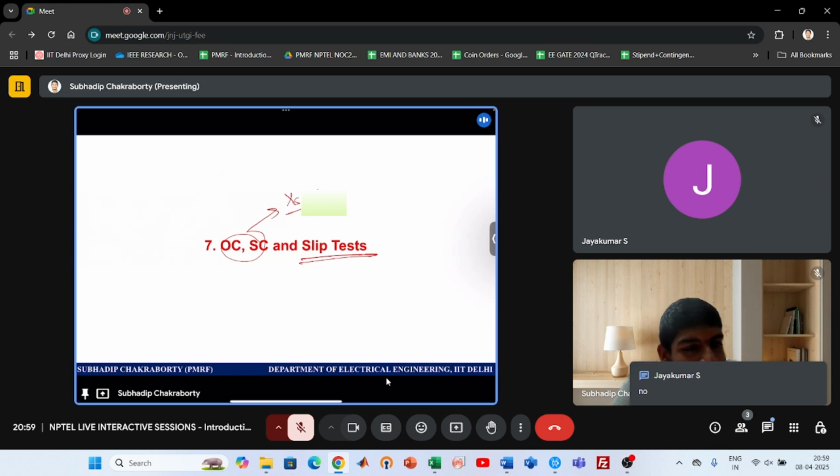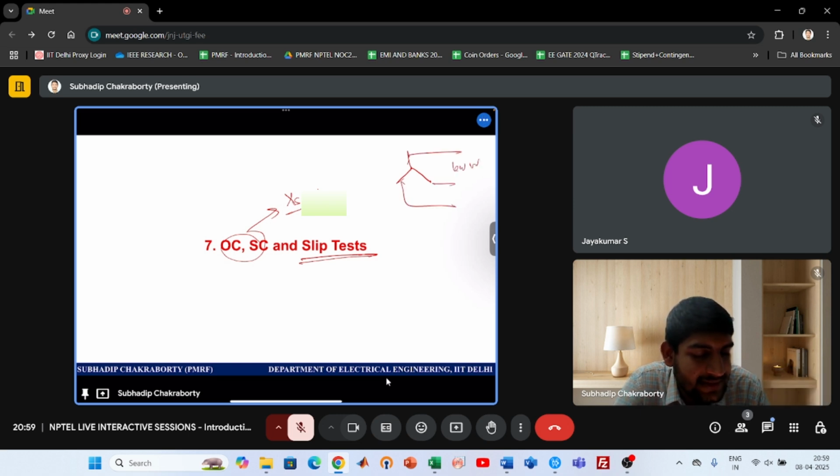The slip test is nothing but a variable reluctance path test, where you have the alternator's 3 coils. You supply them with a low voltage. The field coil you open circuit, and you rotate the rotor at maybe 1400 RPM.